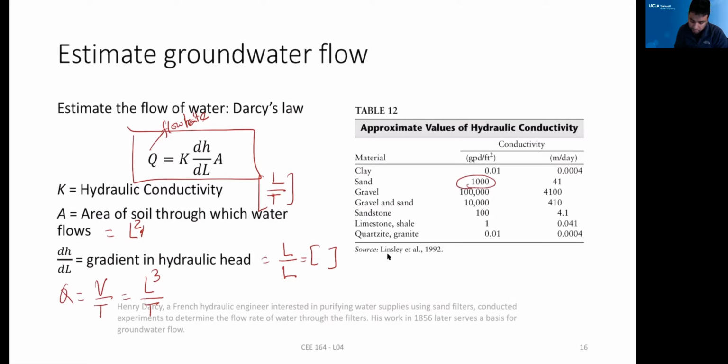And if you look at gravel, gravel is much bigger. Anything larger than 2 millimeters, we call gravel. Okay, that's based on size definitions. If the size is too big, then they have much more void space because they cannot come close that much. Because of that, inside the gravel, water moves much faster. So you have all the other factors there. I can check. Limestone is much lower because it has very small fractures.